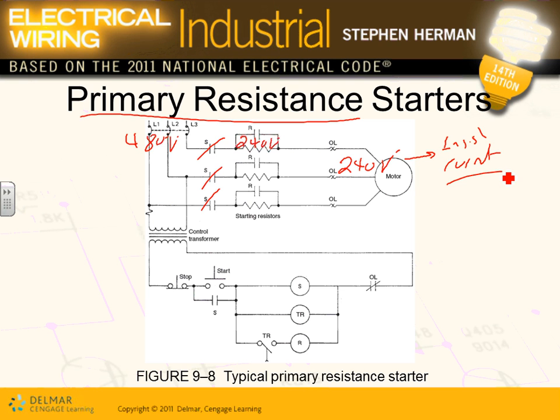Here's the control system for it, guys. You close this one, this energizes, this will close. Now the motor's up and running, and this happens for 10 seconds. There's a timer here; you went through it with Scott. The timer here times for 10 seconds. After 10 seconds, it times out and closes this contact. When it closes this contact, this R really closes, and then bam, bam, bam, it will shunt the resistor, and the voltage here goes all the way to 480. So for close to 10 seconds, guys, you reduce the voltage.